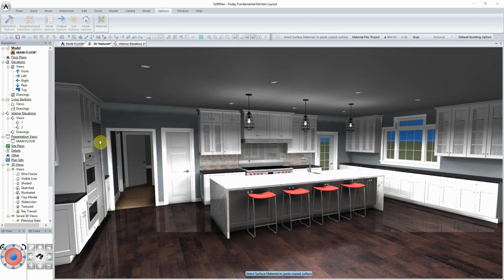And don't forget that you actually have the ability to import those into SoftPlan. As the manufacturers come out with these different symbols, or as you search other three-dimensional symbol warehouses, you can import those 3D files, whether they be SketchUp or AutoCAD, into SoftPlan for use. Maybe the only thing I would warn you on is that sometimes the level of detail on those symbols can cause a bit of a slowdown if there are too many surfaces. That's something our support staff can help you with.